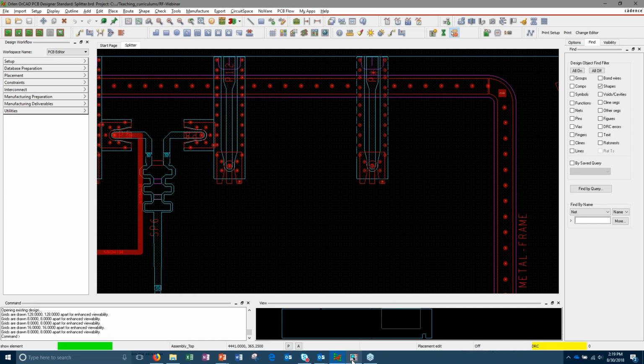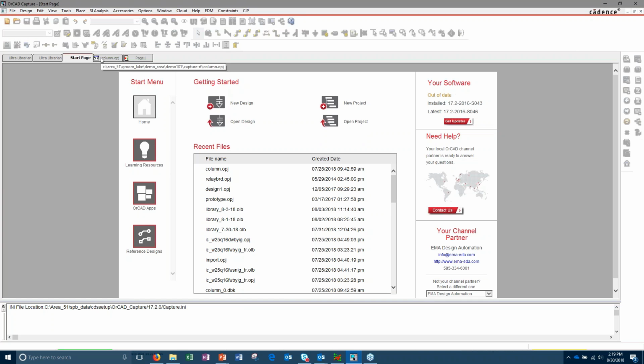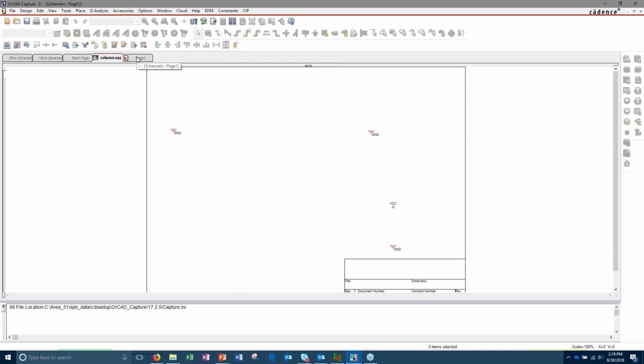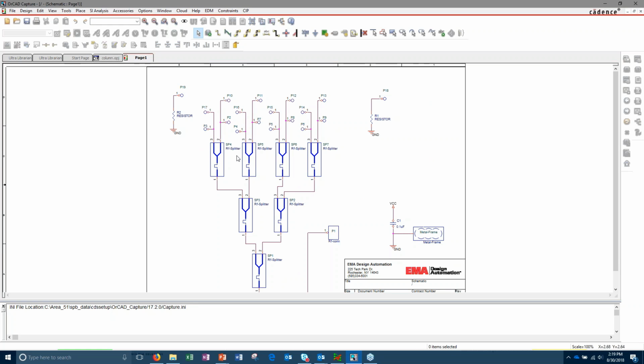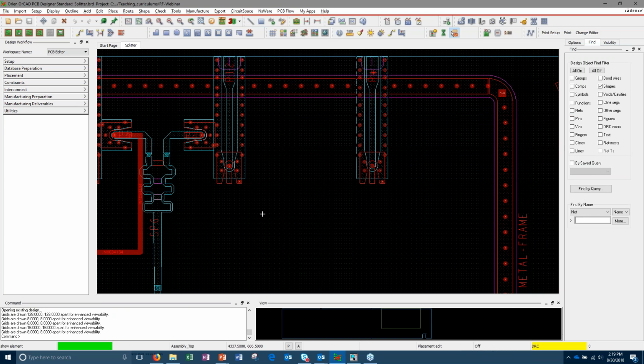But before I leave this, I want to point out that here's the schematic for that. Let's go jump into, there's the design, and here's the page, and here's all my RF splitters, the dividers that I have in there. They are symbols in my schematic, so because I've created them as a symbol in the printed circuit board, the schematic can drive those symbols even though these symbols are printed down instead of purchased parts. And then it just becomes a no pop in bill of material. There's no parts to really populate. Their circuits are printed down.